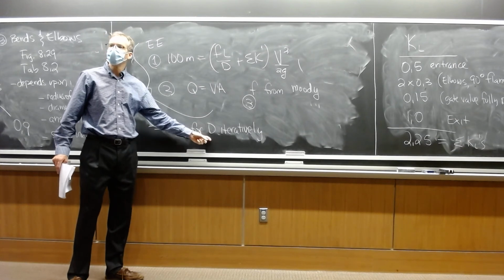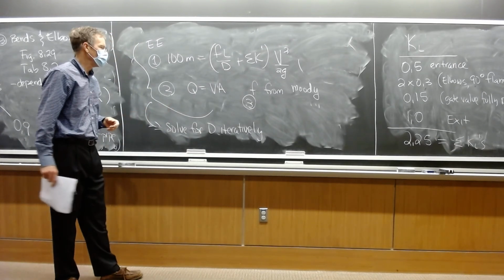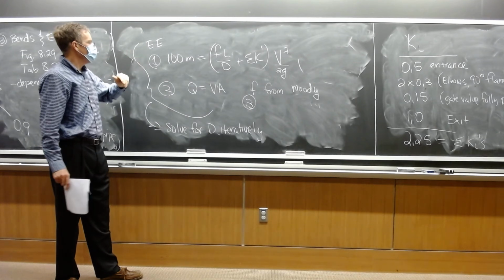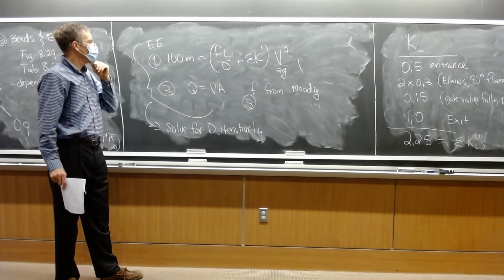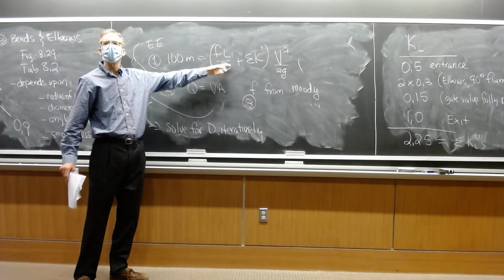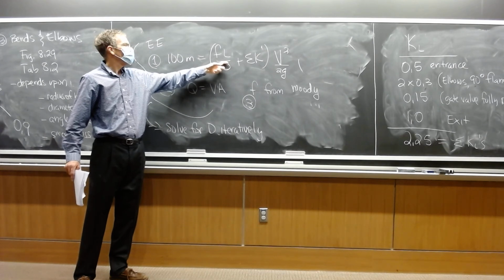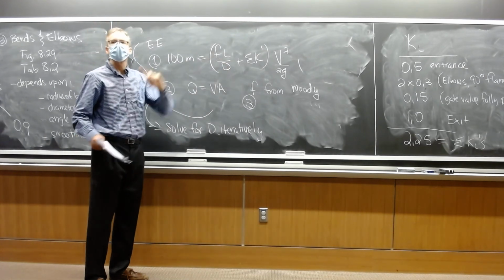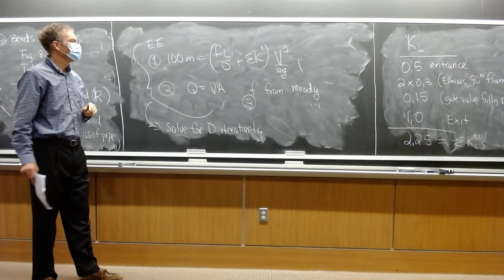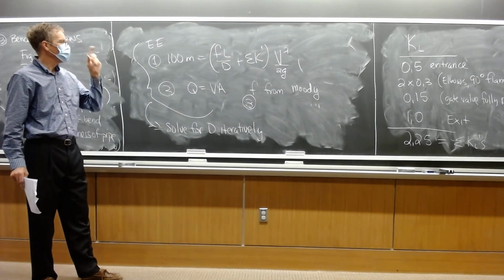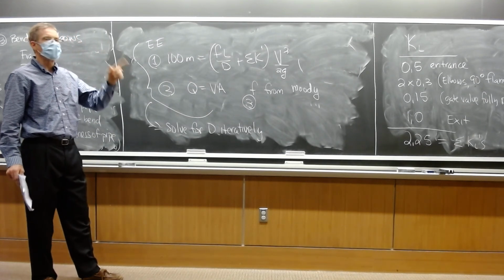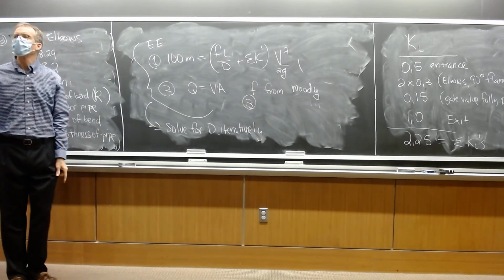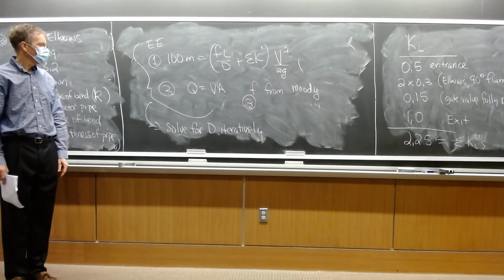This is a type 3 problem where, just like we had done previously, in solving that problem, you'd guess an F of 0.03 and then use this to get the V, or you'd actually do a different version of this equation that has Q instead of V, and then get the flow, and then from there get the Reynolds number, the relative roughness, get an updated F, and go around again if you need to.